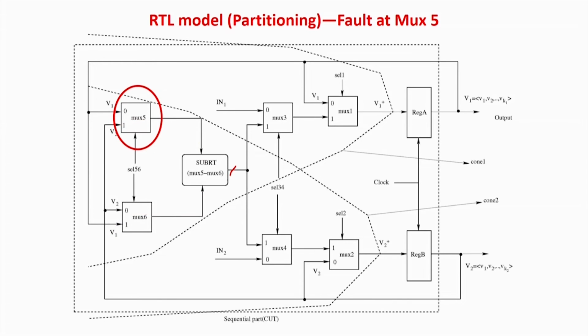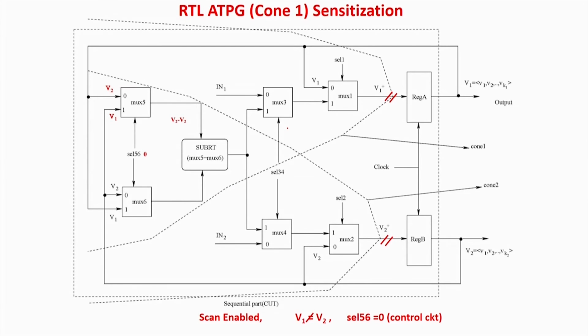this is basically a crisscross fault. So what is going to happen? I am going to have the answer V1 minus V1, or V2 minus V2, instead of V1 minus V2 or V2 minus V1. That is the problem that is going to happen, and that is actually the fault over here. So I have to go again for the same business: sensitize, propagate and justify. The same philosophy will apply. Let us see how it happens.